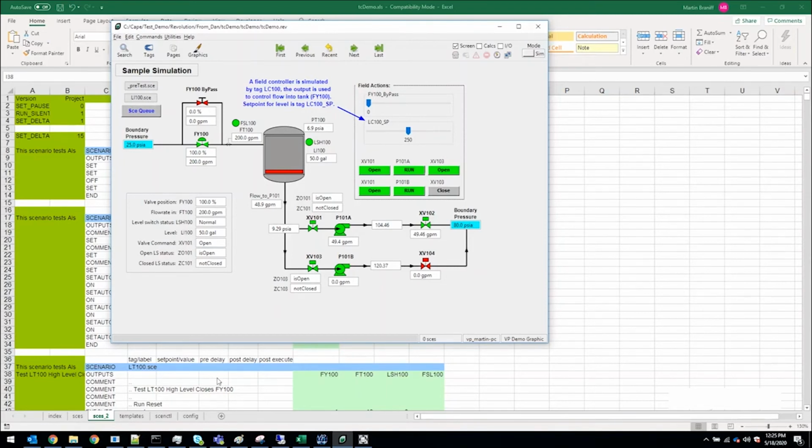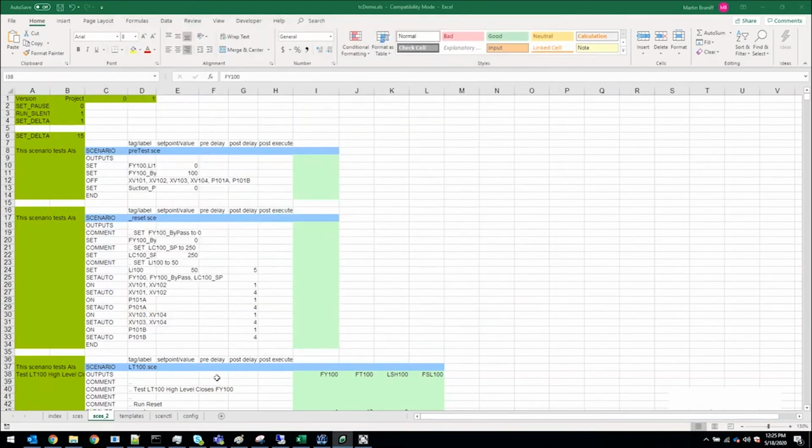In addition, these scenarios or cases can also be readily executed sometime in the future, in the event change is made to the control logic. This helps demonstrate that the changes being made have not affected the integrity and function of the original control code.